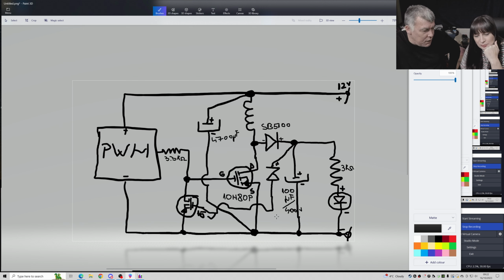Just forget the rest of the schematic. Just focus on this. So what do I want? I want to switch this signal to ground. It's the PWM output, right? So how can I switch it to ground? I'm adding a switch. This MOSFET is a switch. In order for this MOSFET to switch, I have to have in the gate more than 5-6 volts. So if you have 15, it's fine. They are working up to that. So what is not clear and what you don't understand, you have to tell me, because if you don't tell me, I can't explain.